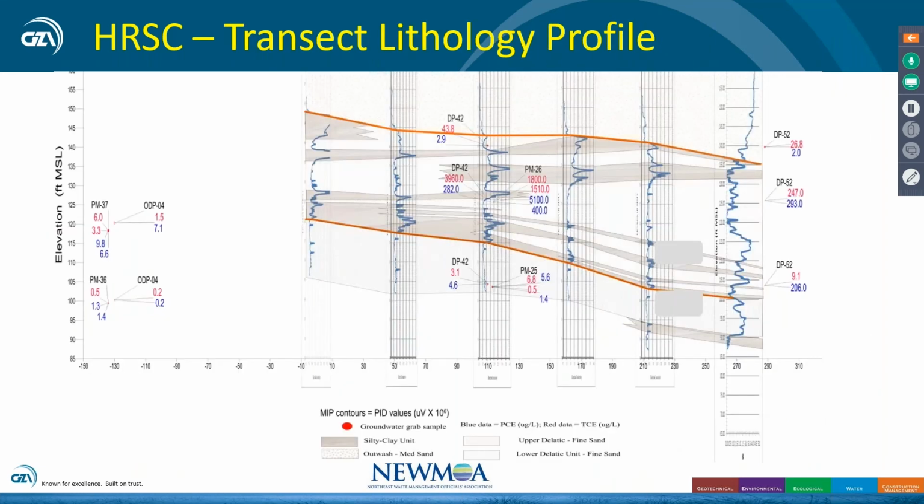This was information that we were provided prior to getting involved, and through some of the high resolution. The orange lines are boundary conditions of clay, and clay in our case is inches and not feet. In the middle, we have thousands of parts per billion of chlorinated solvent, specifically TCE here. And what we found was a nice high concentration where we were going to treat, and a boundary condition at the bottom where the greatest concentration was 4.6 parts per billion of TCE.